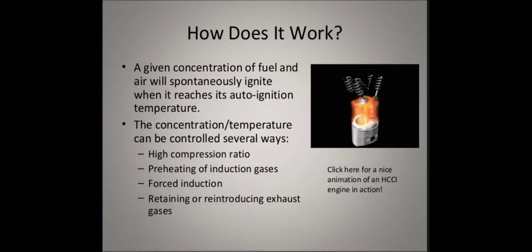How does it work? A given concentration of fuel and air are spontaneously ignited when it reaches its autoignition temperature. The concentration and temperature can be controlled in several ways: high compression ratio, preheating of induction gases, forced induction, retaining or reintroducing exhaust gases.